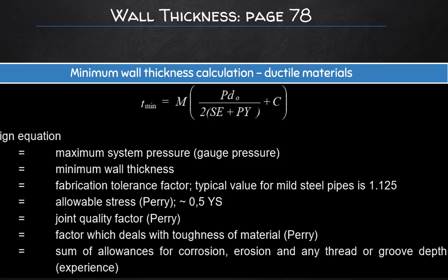So high pressure pipes are generally used for steam lines, which are considered as thick cylinders, or else if you have a very high pressure reaction that you are doing in a reactor, then you would use what is known as thick cylinders. Cylinders are just referring to the fact that the pipe geometry is a cylinder. Schedule 40 pipes are generally used. They are the most commonly used all-purpose pipes in industry.